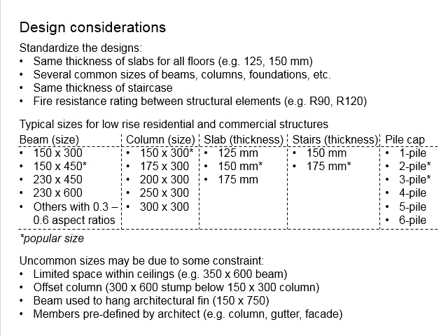The reason the engineers will go to big slab size is with the intention to reduce the amount of beams in the structure. You know that the fabrication process for the beam is more tedious, as it involves the fabrication of the shuttering. The steel workers need to produce a lot of shuttering, which if you use a larger size of slabs, by increasing the thickness of the slab, the workers do not need to produce, and the reinforcement bars just simply lay onto the slab, and then casting can be made.